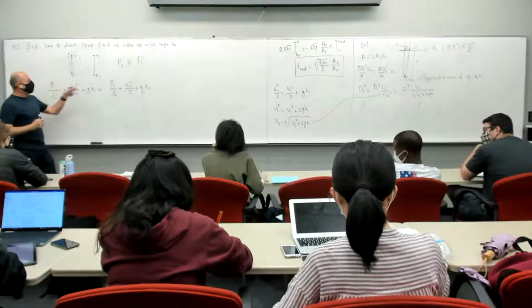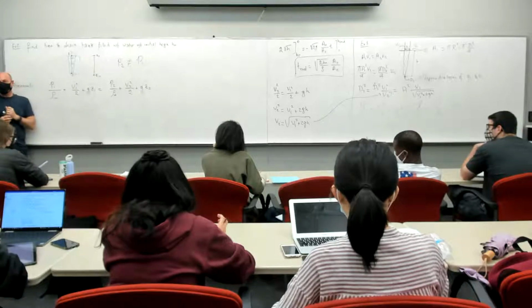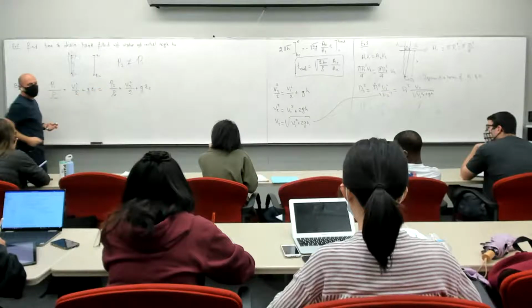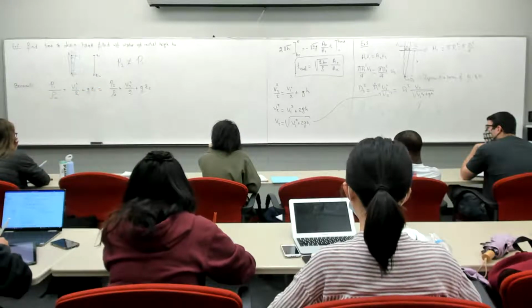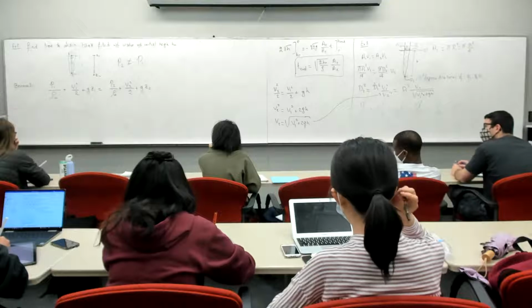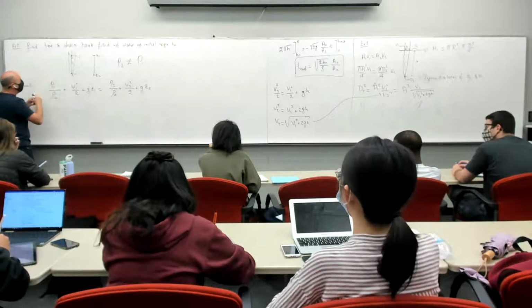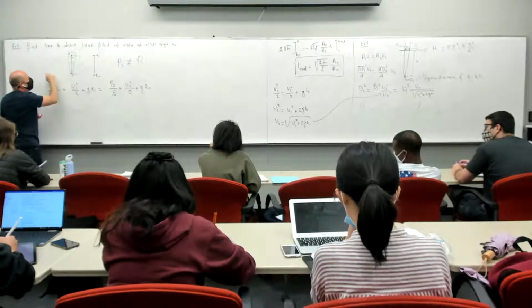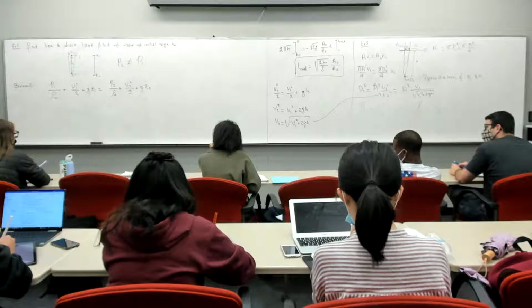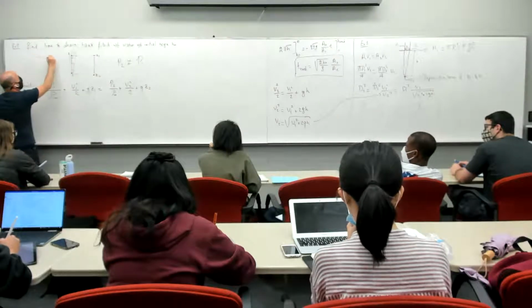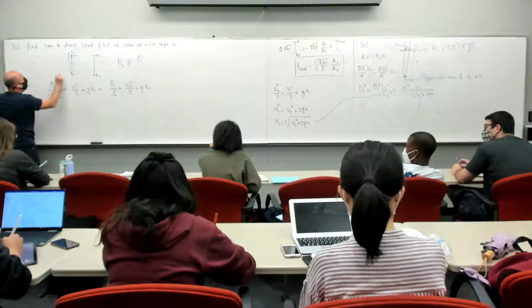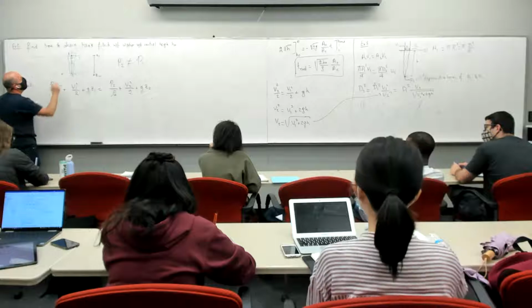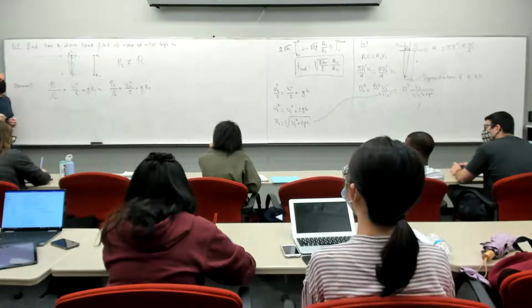So you have 3 unknowns in one equation. Or you have 2 unknowns and one equation, because all you need is P2 minus P1. So what do you do in this case? There's a little trick from statics. From statics, we know that the pressures at the same level must be equal. So the pressure anywhere at this level, the pressure here must be equal to the pressure over here, and the pressure over here must be equal to the pressure over here.